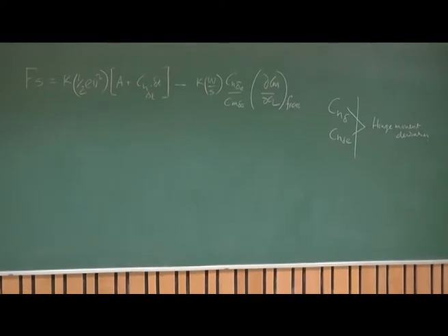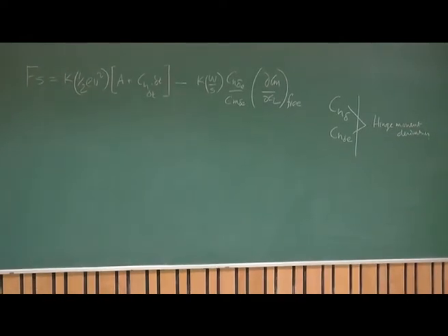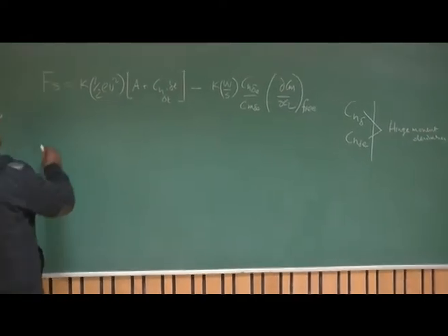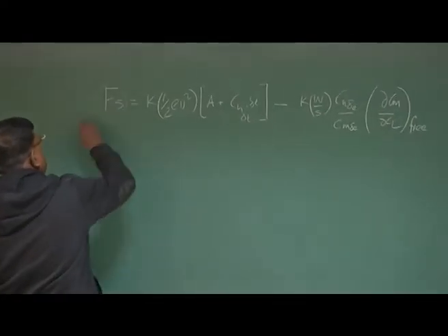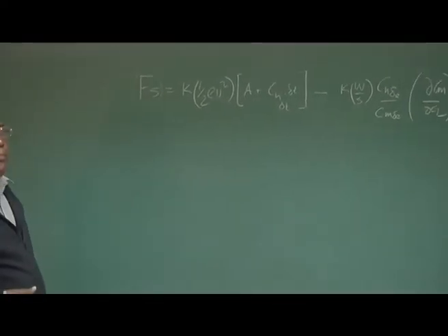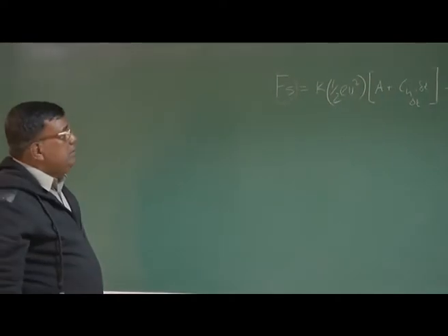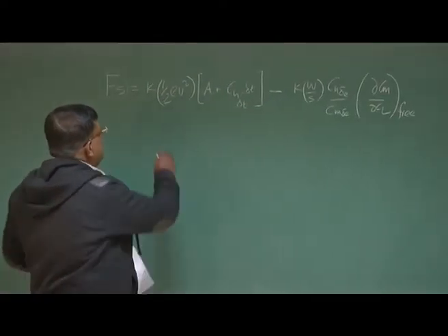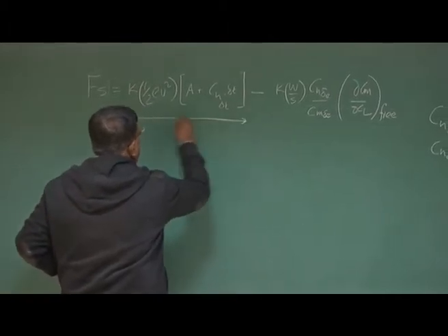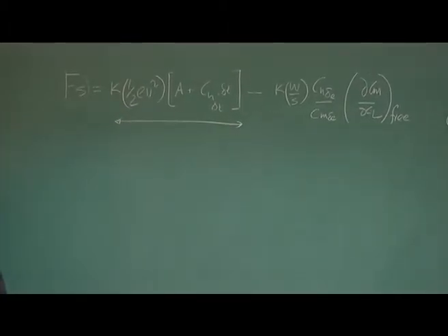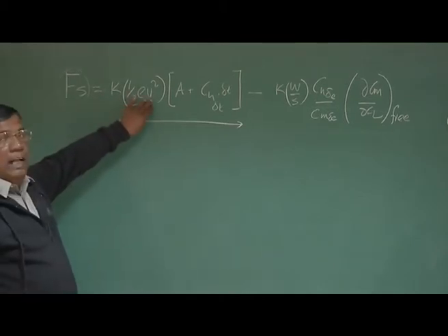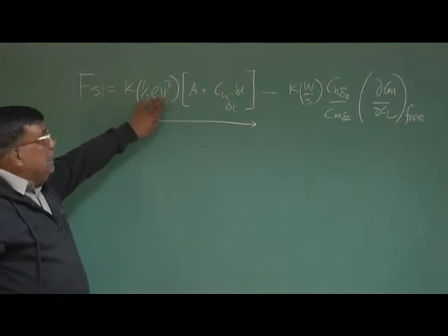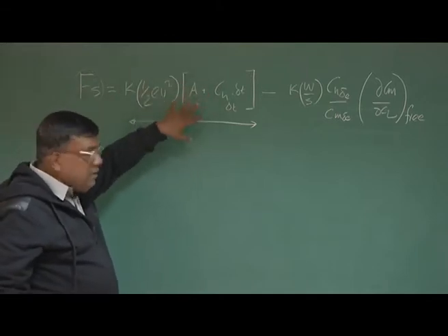Now come back to this expression. What does it tell you? It tells you the stick force required will vary with dynamic pressure, and the first term is the only one concerned with speed. The stick force depends on speed or dynamic pressure, and that contribution comes only from the first term.